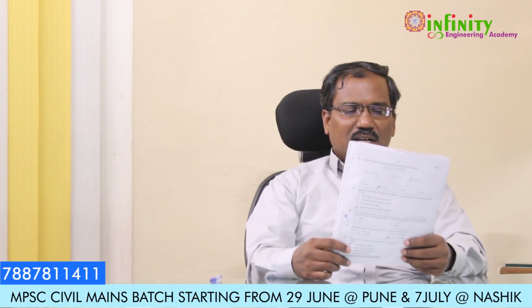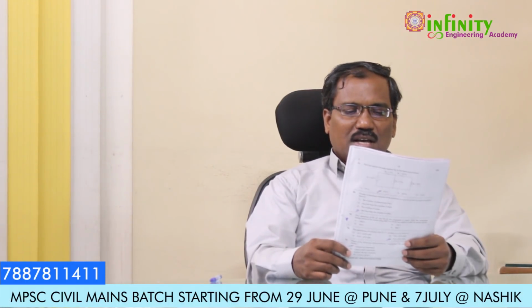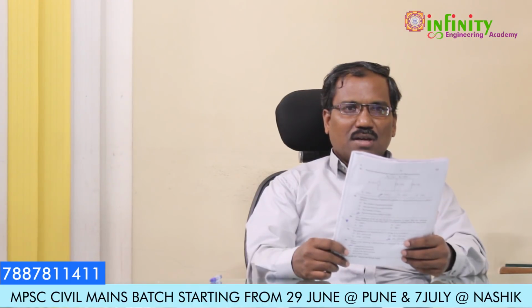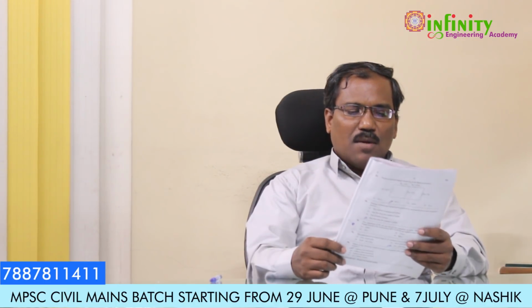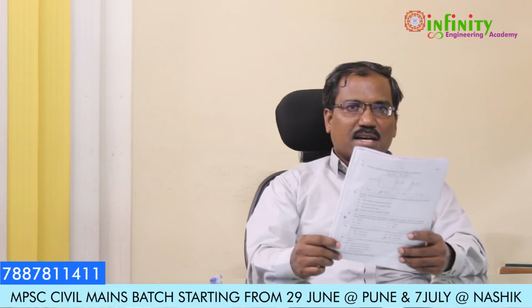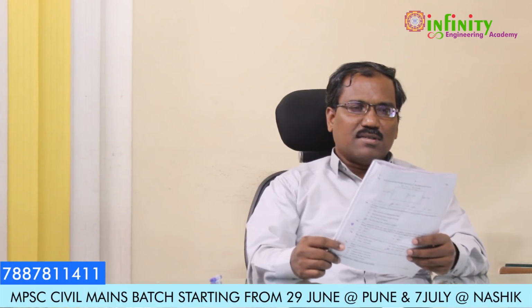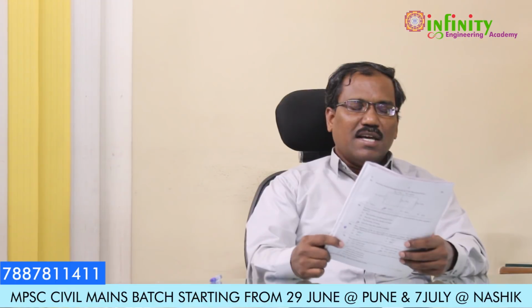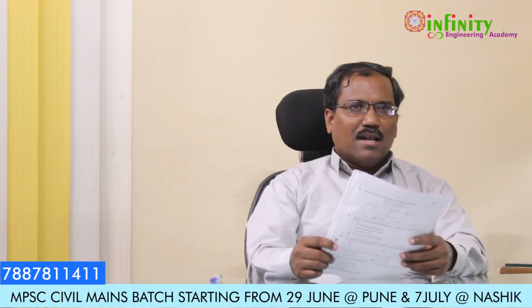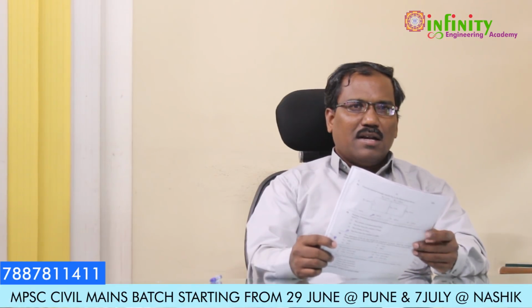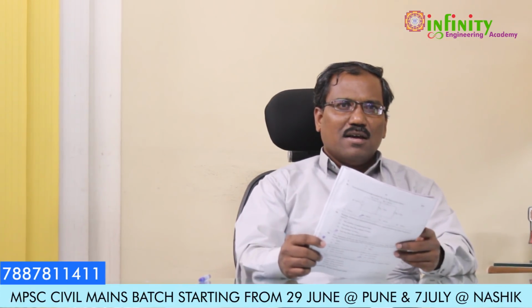And the next one is that dash is a process by which great pressure is applied to a heated metal billet or blank, causing it to flow through a restricted orifice. Among the options, extrusion is the correct one. In the extrusion process, we heat the billet to a very high red hot temperature, and under high pressure the metal billet is forced to flow through a small orifice. So that is called the extrusion process.